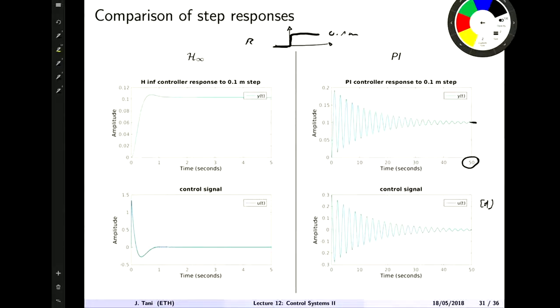And it also shows, we know that if the phase margin gets smaller, then we have less robustness in our design, right? So this is also a statement that we are close to instability. If something unexpected happens, if the model changes or whatever, then we might get unstable. With H-infinity, after 5 seconds, we are converged, so it takes actually just 1 second, and we manage to have a control signal which is still decently small, so we don't exceed 1 ampere. So I think this comparison is a clear statement that this method is quite interesting for controlling difficult systems.